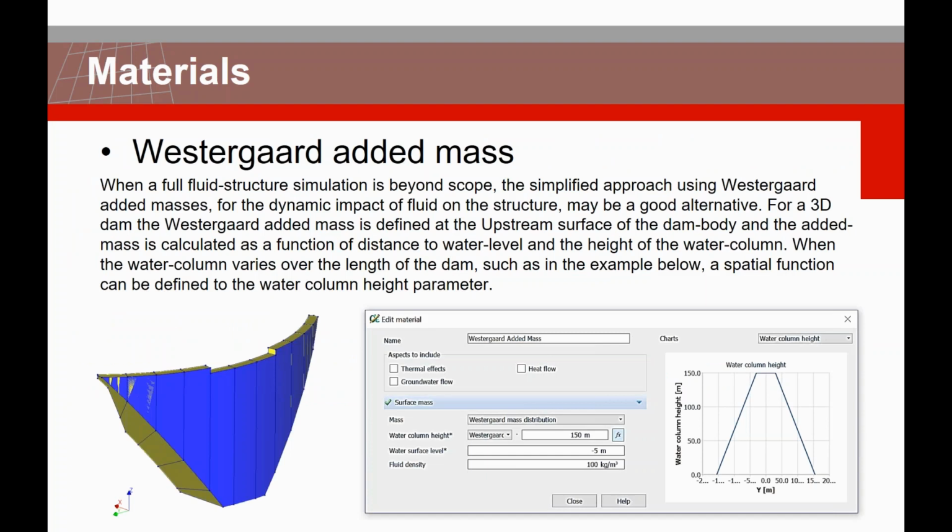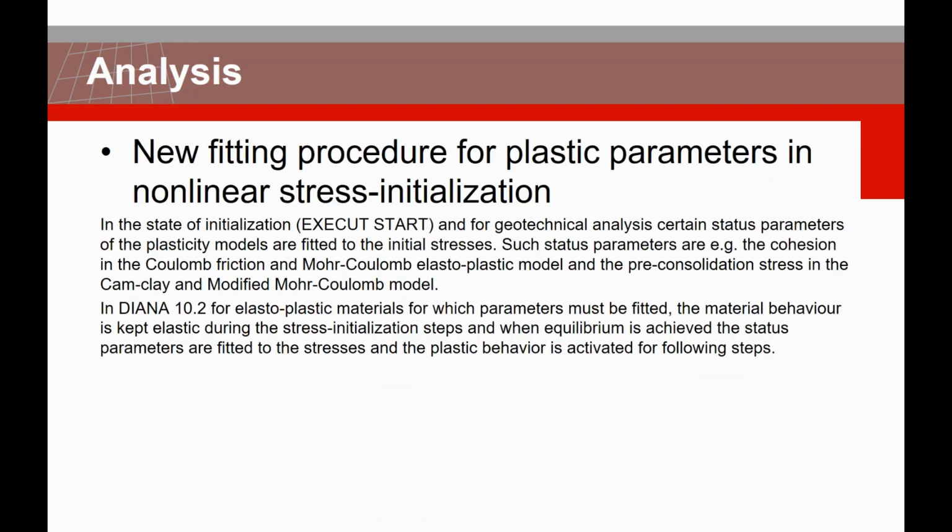For modeling the reservoir mass on hydraulic structures, we made the Westergaard added mass input available through the GUI, so it's very user-friendly. Now the user can select the effective phase based on the corresponding height, based on the reference properties of your fluid. The program calculates the distributed mass from the reservoir, and you can go through the analysis based on this approach.